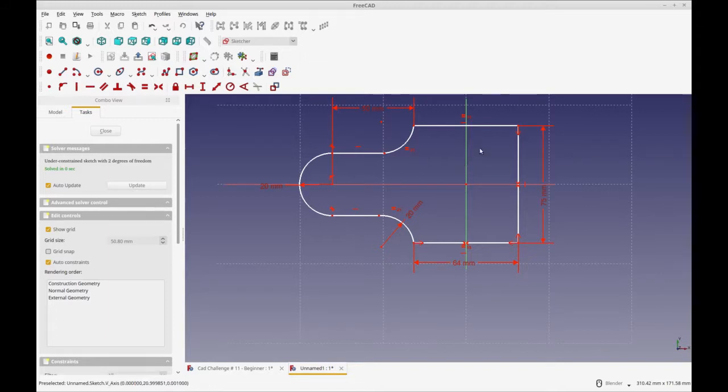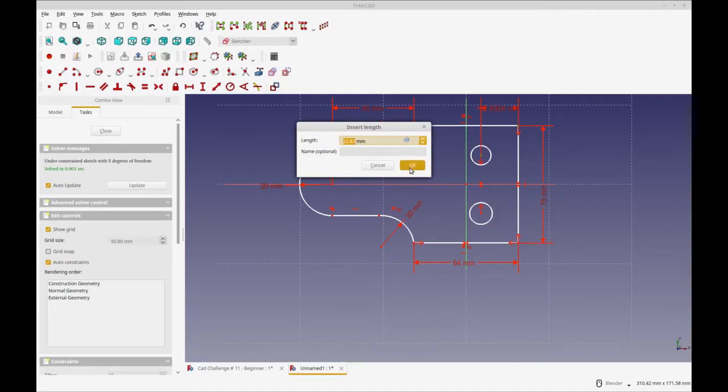So the next piece I add are the two holes in the diagram. I've got to move back to regular mode and add two holes. Now these are not going to be constrained to this x-axis because that's not the distance they're at. They are going to be mirrored, or symmetrical, though. So you'll notice the symmetry not only makes them symmetrical distance, it's also in alignment in this direction. So now I'm going to do a measurement, a distance constraint here, a horizontal, and I think that was 27.